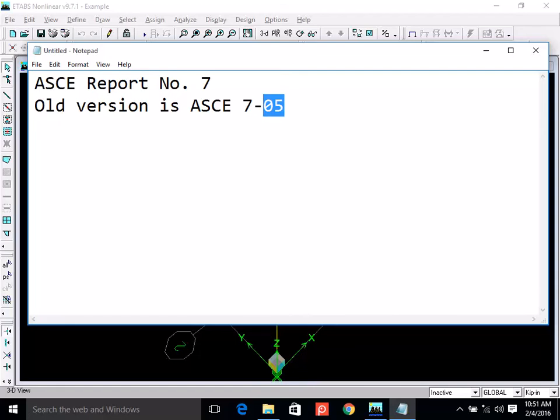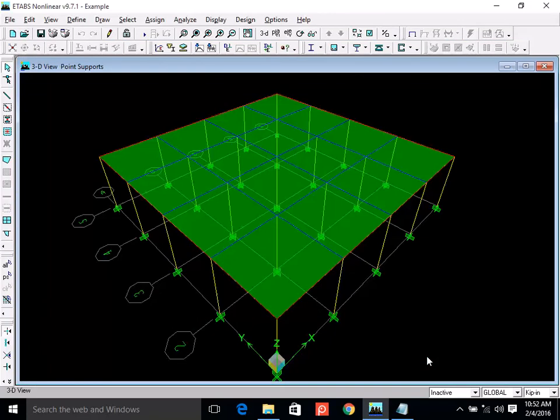There is a table in this report which tells you the magnitude of live loads or occupancy loads for different purposes. And I think you can also find this in your reinforced concrete book from Dr. Zaid Ahmed. So you can simply look at your architectural plan, look at the use of that panel, go to that table and write down the load.